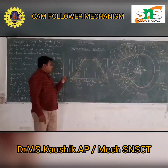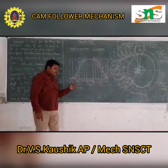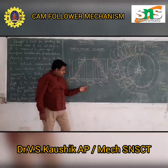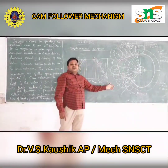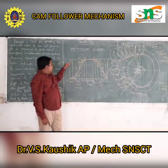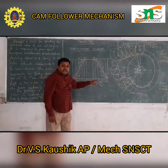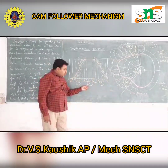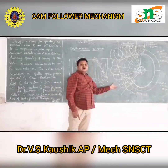Now convert the scale ratio: 60 degrees means you draw a 6 centimeter line, and 20 degrees means a 2 centimeter line, and once again for 60 degrees a further 6 centimeter line, and a rectangle will be formed. See, 37.5 mm height, and from here totally 14 centimeters distance you should draw. First 6 centimeters is the outward stroke, next 2 centimeters is the dwell, and the remaining 6 centimeters is the return stroke.